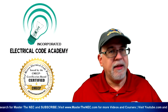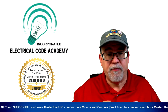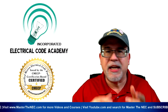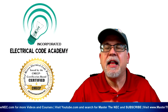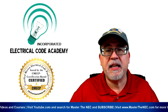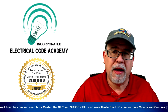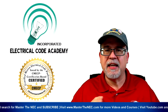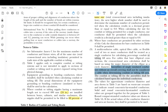All right. In this case, they're trying to gain an advantage. It's still going to be 40%. Even if there are 4 conductors and you plex them or twist them together, it doesn't matter. It's not a cable. You can't use 53%. It's still 40%. Okay. Keep that in mind. That is reserved for things like NM-B, tray cable, MC cable, AC cable, all those types of things that you can pull in raceways. There's no problem with that. But you can't exceed the 53%. Just taking individual conductors and twisting them doesn't make it a cable. Okay? Just keep that in mind.